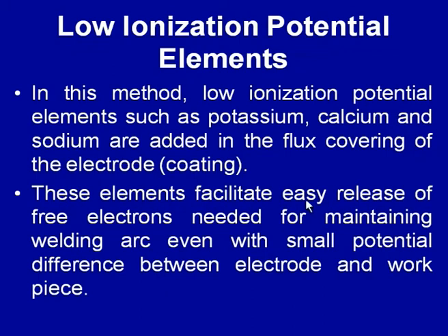So, these elements facilitate easy release of the free electrons required for maintaining the arc even with the small potential difference that exists between the electrode and the workpiece. So, this is an important aspect that is used when using AC current for welding purposes.